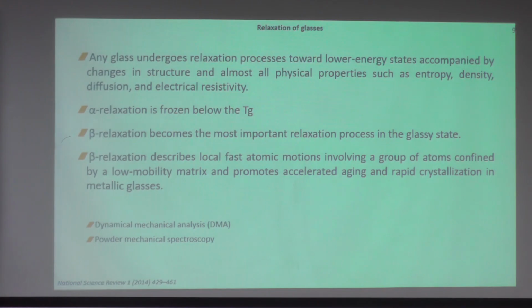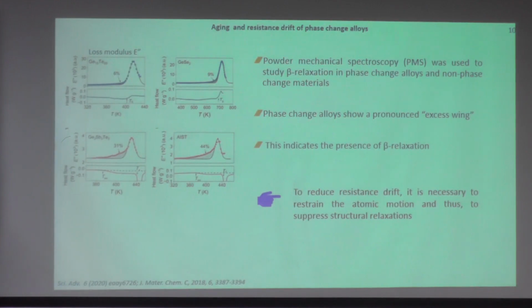So let us look at the results on powder mechanical spectroscopy. This is a technique used to study the relaxation behavior of materials, particularly phase change materials or non-phase change materials. You study the loss modulus E'' here, how it behaves.